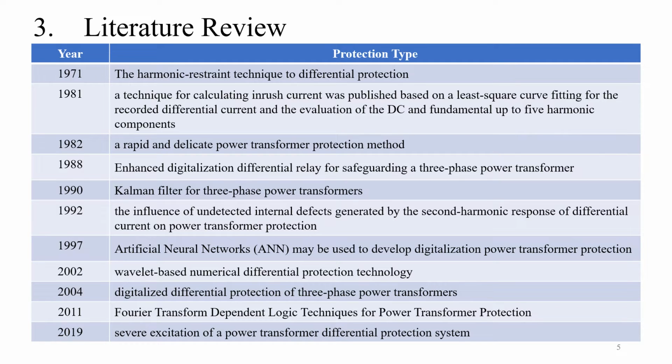In 1988, an enhanced digital differential relay for safeguarding three-phase power transformers was designed and built using Kalman filter theory. In 1998, Kalman filters for three-phase power transformers were developed and implemented in real time utilizing a digital differential and earth fault avoidance technique. The fundamental, second and up to fifth harmonic components of the power transformer current were determined using 11-state Kalman